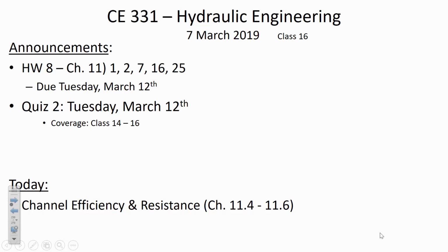And there's two aspects to that. There's laying out the location of the pipes so that you minimize the overall length of pipes that's being used. And then there's optimizing the size of the pipes. Now, of course, optimizing the diameter of the pipes is going to depend on what flow rates you assume is coming out of the network. We'll talk about that a little bit in a minute.